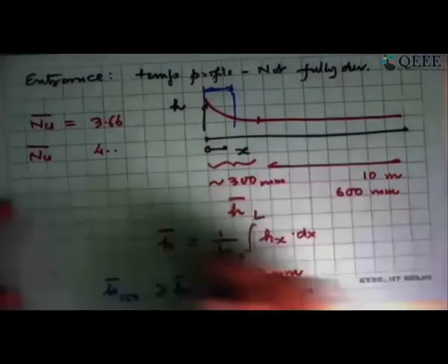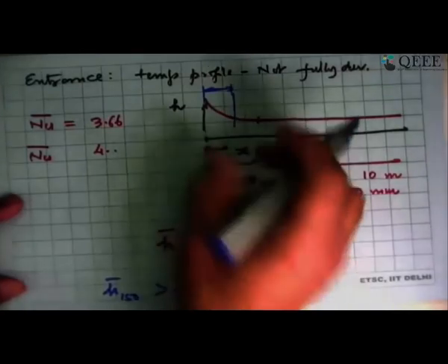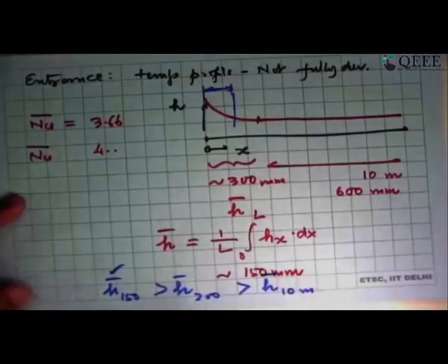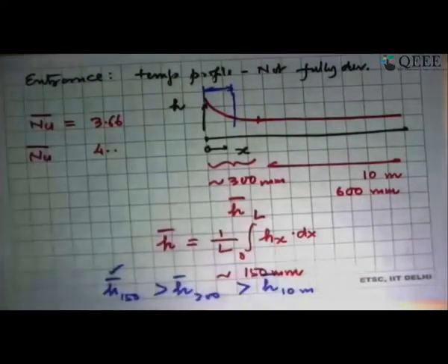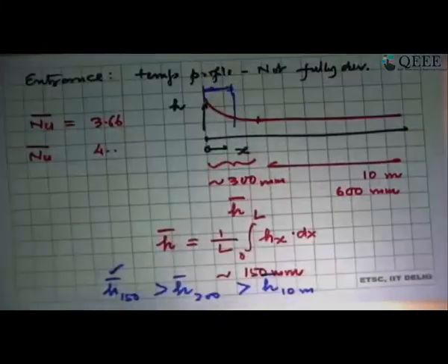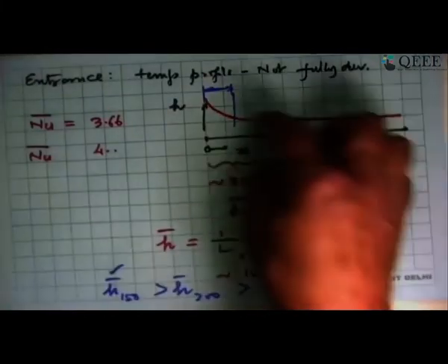So if you do that, you now have the advantage of the heat transfer coefficient increasing, and so your total heat transfer area requirement goes down. That's the type of trade-off people do, and finally you get an engineered product like, say, a radiator or the evaporator or the condenser of an air conditioner, where there's a certain length of tubes, and then you have calculated what will be the heat transfer on it.